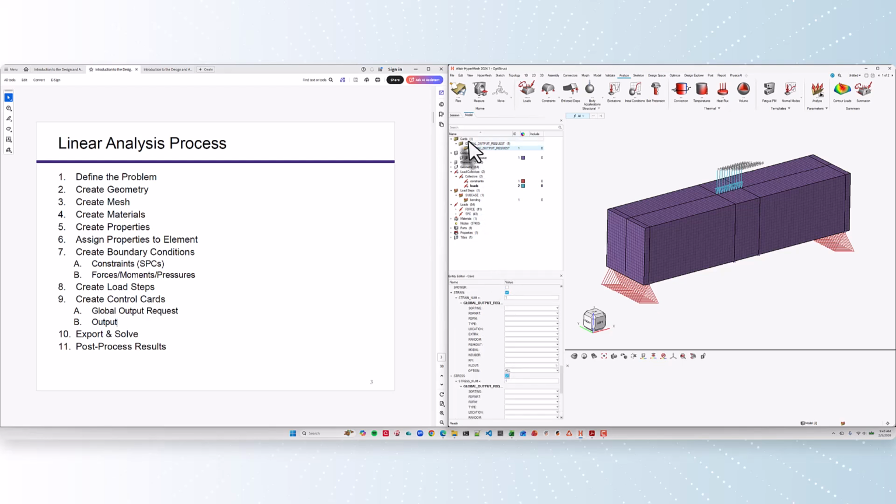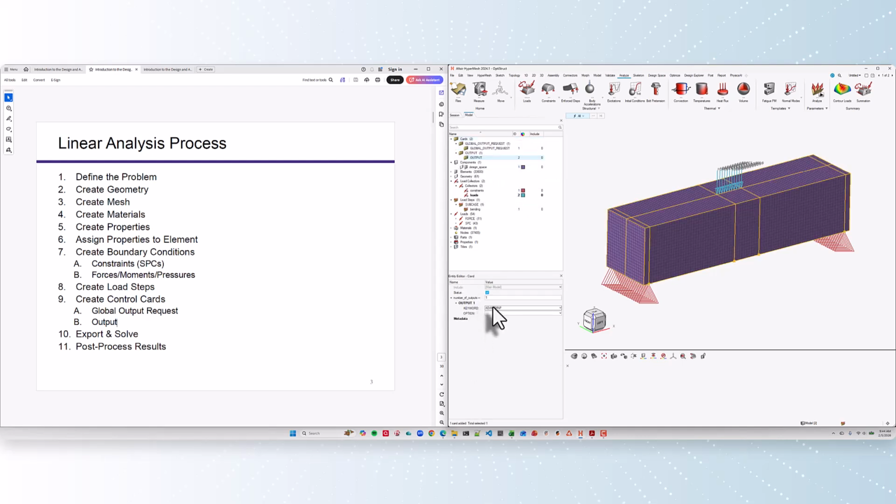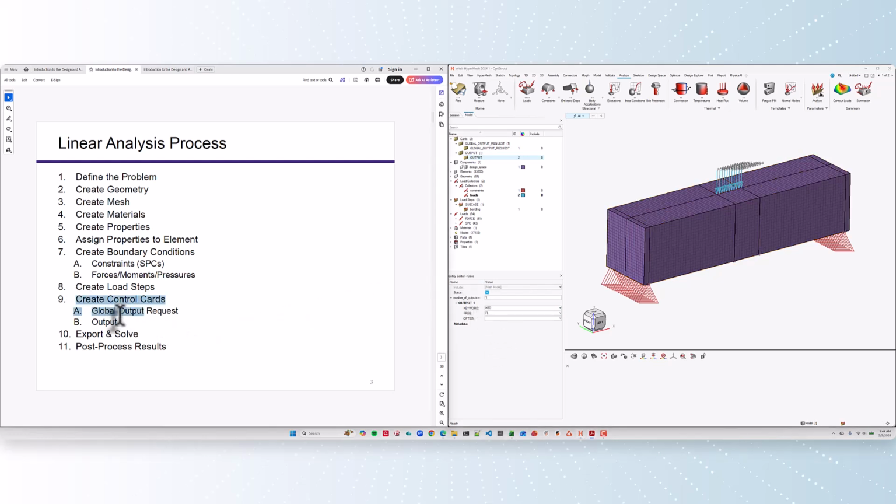And then I want to specifically ask for a particular format. So if you just right click on cards and say create, you'll get this other output, which allows you to pick a specific format. The format that we want is H3D. You got to pick it twice. So make sure you pick it twice, a little bug. Okay, so I've gotten through all of that.